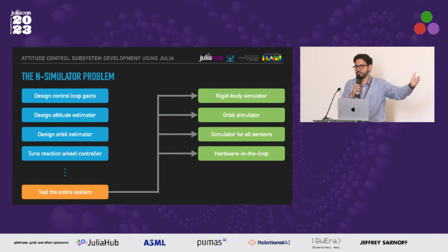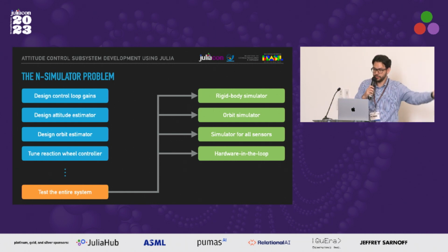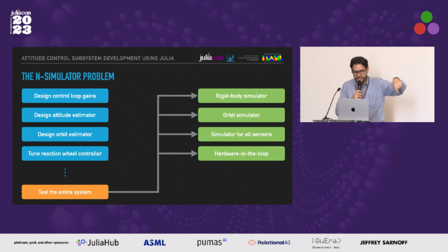We wait for the last phase, where we have this hardware in the loop test with validator simulator. If something goes wrong, okay, let's redo the software. But it costs a lot. The simulator on that phase happens in real time. If we find some error in the software, we have to go back, emit a new version of software, and pass the entire validation campaign again to test for regressions. So it costs a lot.